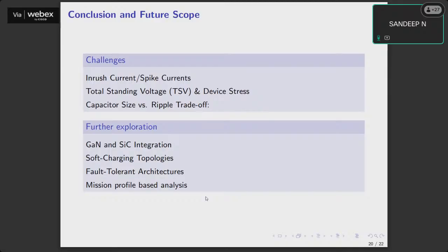The inverter should be such that the devices have thermal balancing, because even if one of the devices is thermally not good, there could be a fault, and it is going to create a problem. Okay, so those are some of the areas that can be looked upon when we go for an inverter design.